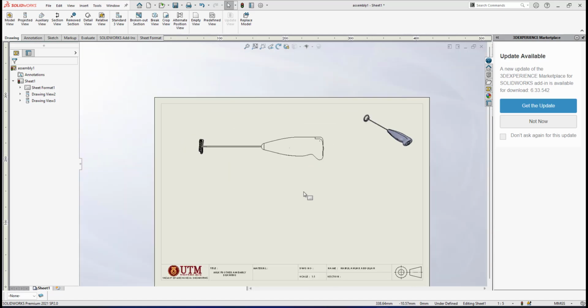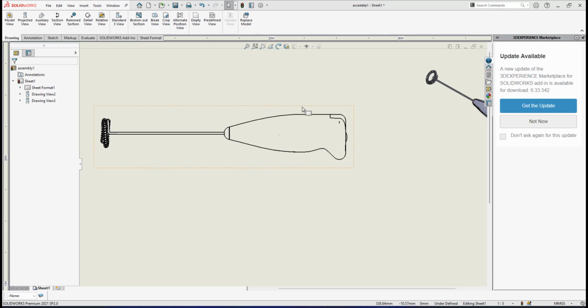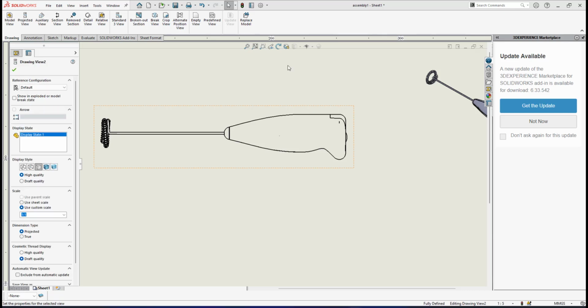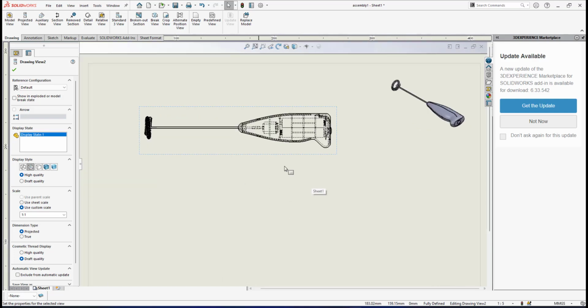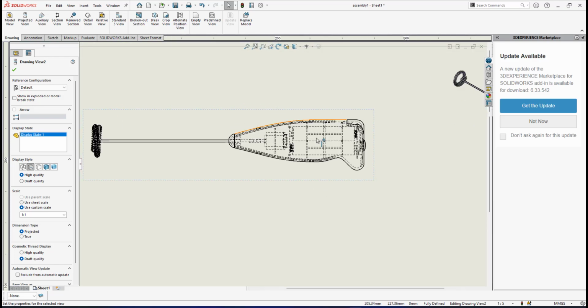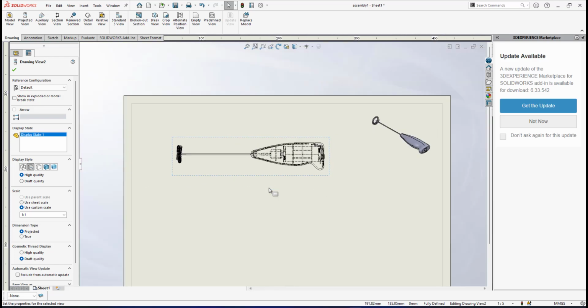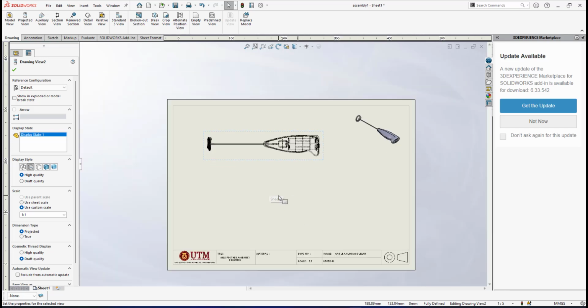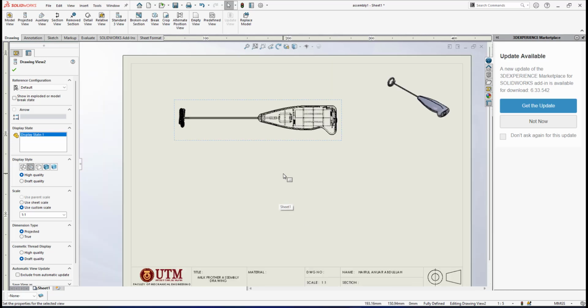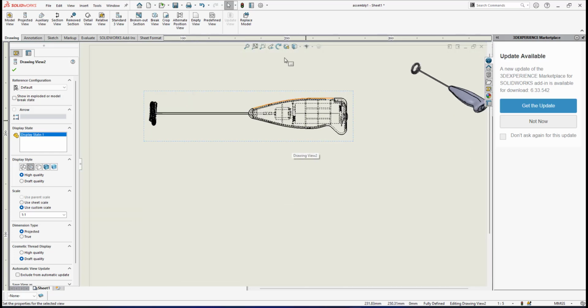Since this is the top view, we have a cutting plane. When we do assembly drawing, we try to avoid any hidden lines. For example, I cannot select this view under display style and go for hidden line, so this is not correct in assembly drawing, because we have to make the assembly drawing a simple version so that the viewer of our drawing can easily understand our product. So that's the idea. I remove the hidden lines and show only the visible lines. That's why I do full sectioning.